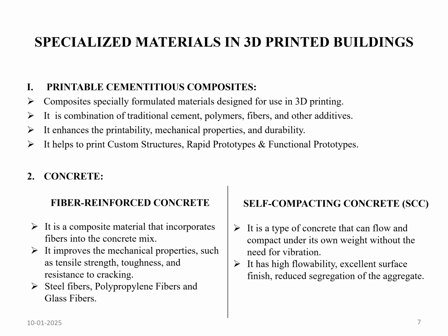Second is self-compacting concrete. It is a special type of concrete that can flow and compact under its own weight without the need of vibration. It has high flowability, excellent surface finish, and reduced segregation of aggregates.